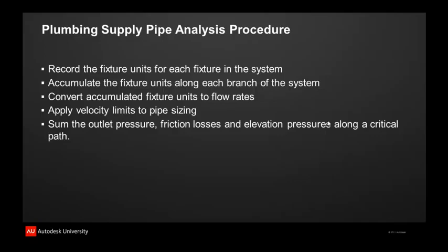This allows us to know the total flow rate for an entire building before we even start to size the pipe, because it's fixed by those fixtures. And often the sizing of the pipe is not based on friction loss so much as it is on the velocities.